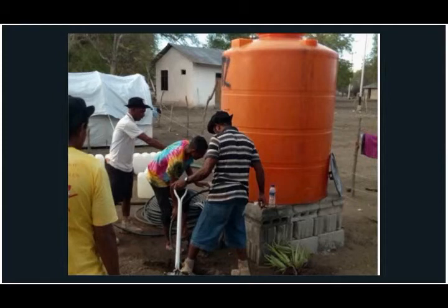It's definitely what we're dealing with in Cox's Bazar at the moment, where we have a lot of groundwater pumping. And I've just come back from a meeting this morning which was discussing how we're managing that, the modelling that we're doing, the data that needs to be collected in order to correctly calculate what that is. So it's actually a very tricky question, and obviously we would want to know what the aquifer is before we start pumping from it, but in an emergency situation, sometimes that's not possible. Sometimes we start pumping and we have to work backwards to try and understand what the aquifer properties are. But it's a very tricky question.